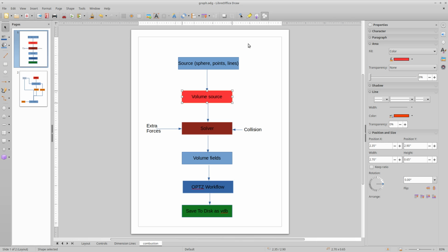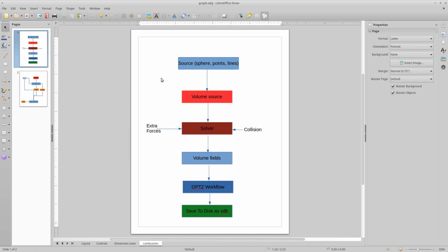Let's say we want to emit an explosion. Okay, we can create our own spike system, our own emission system. You select a point and then it creates lines, and then you randomize those lines and you create cones, and you place them on top of these splines and convert those cones into volume. You then create velocity, and that will be your source.